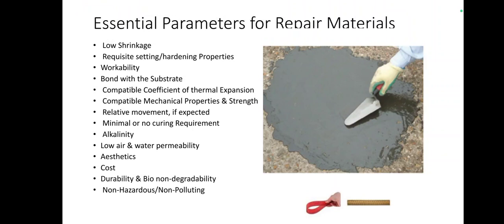And the next one is relative movement, if expected. Suppose any movements are required, like where we are using elastomers; then the repair material should also allow relative movement. It should not be like a mastic, a stiff material, a solid material.